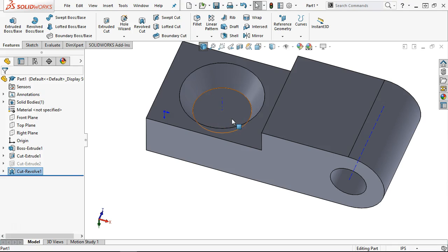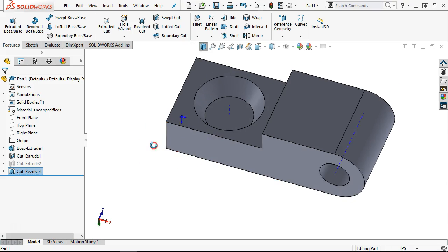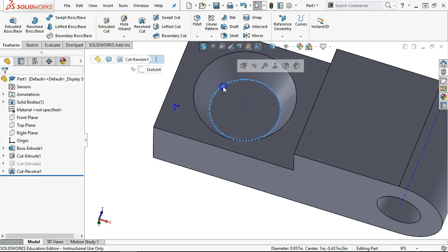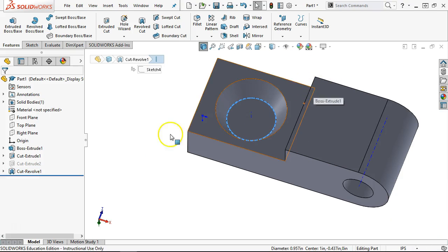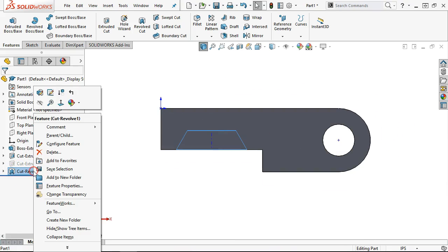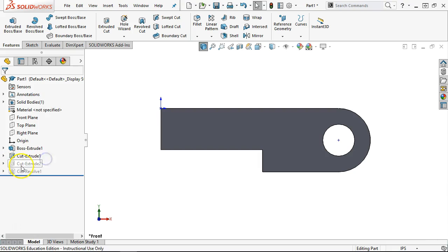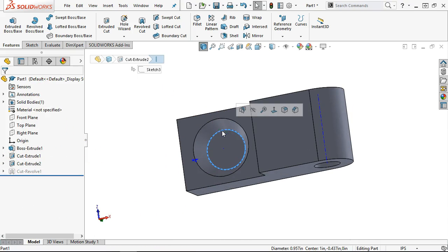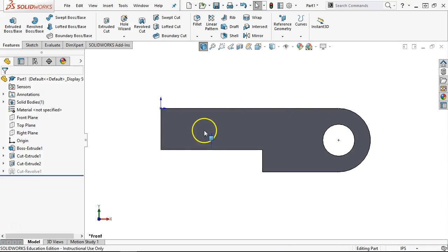So if you can recognize it as the revolve and get the geometry in, revolve has some advantages. Draft may be a little easier, but I don't know that it's doing any better. So 0.957, let's go ahead and suppress that one. Oh, I did normal 2 again, suppress. And then we'll unsuppress the other one and see if they come out the same. 0.957. Similar geometries.